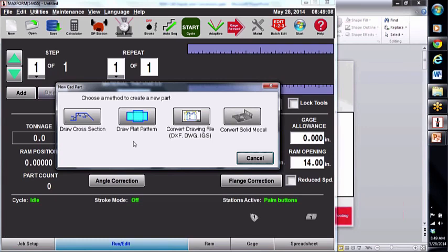When you take it further by adding additional flanges or additional tabs, additional notching automatically appears. It's actually a very clever little way to do a rectangular part if you don't have a drawing system. But a 5-sided part or a part with holes, on these first 2 methods, those won't work.